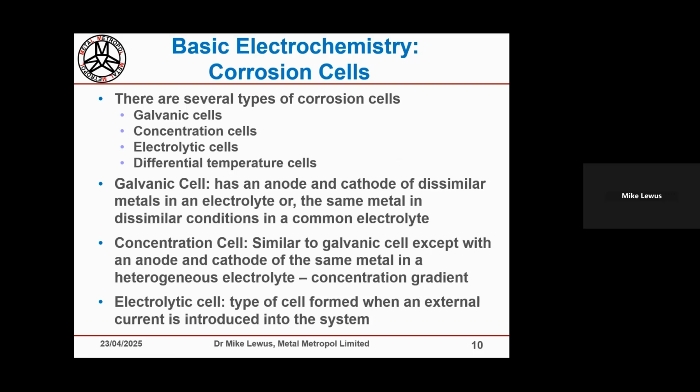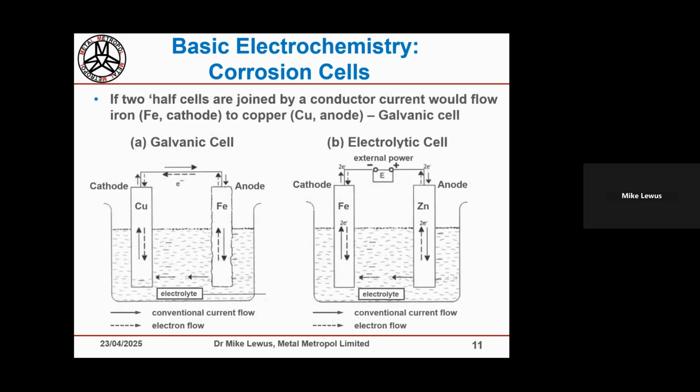So we're really interested in corrosion that occurs because there are two metals immersed in an electrolyte, seawater, particularly of our interest, or it could be river water or brackish water. And when that happens, because of these electropotential differences, we get a driving voltage. In a case like this on the left, we've got iron and copper connected by a hard metal connection in the air and by an electrolyte on the other side of the circuit.